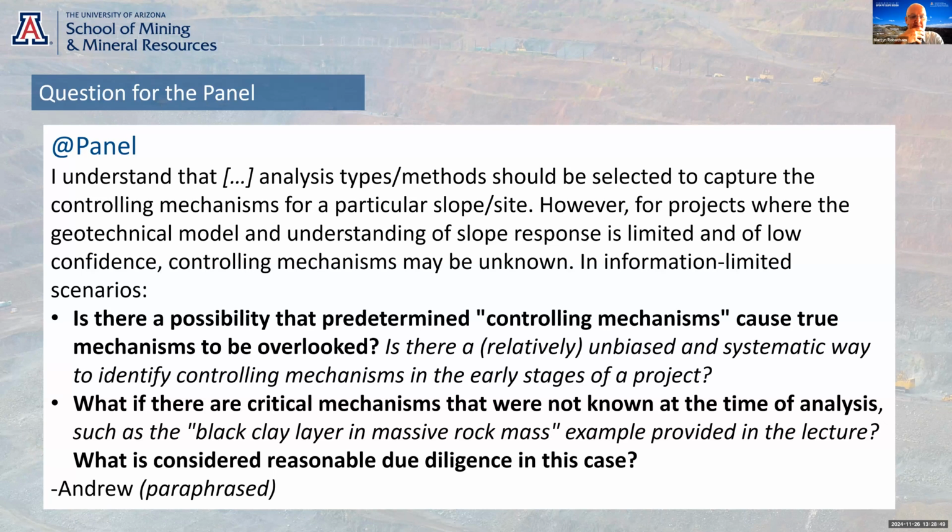When I look at these things, if there is a deformation or if there is a slope you're looking at, you've got to have that concept of structural geology, materials, water, and stresses, and what could occur, and then basically build up your model on the basis of the data that you have. And if you still have a lot of possible unanswered hypotheses, you need more data before you can make a decision on what's actually going on in terms of that controlling mechanism.